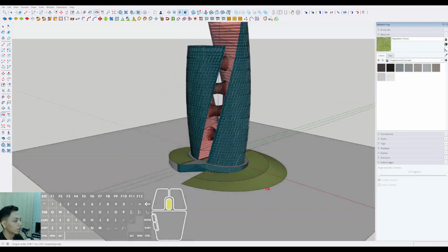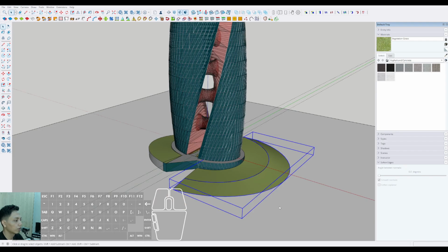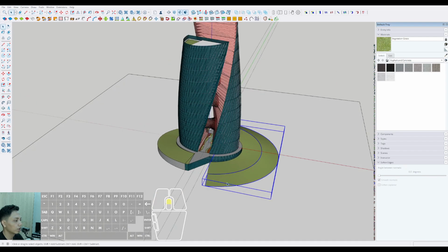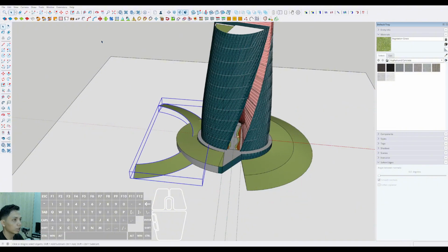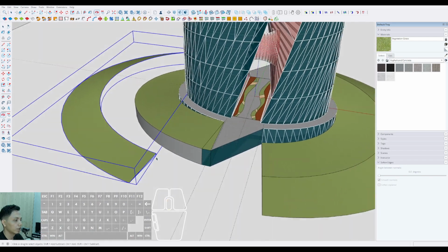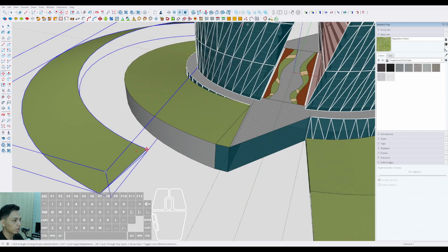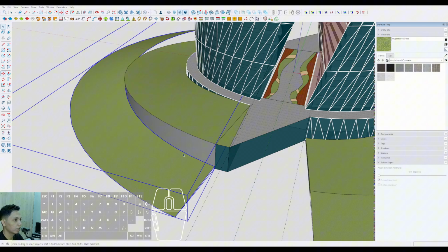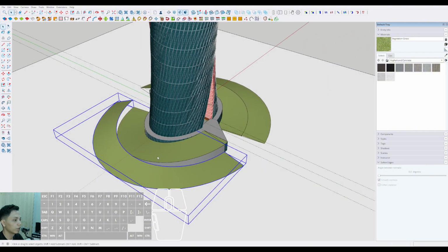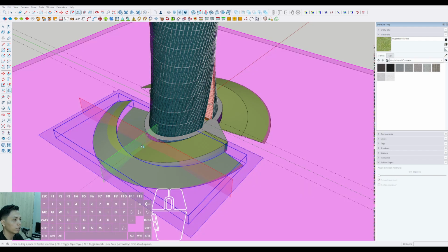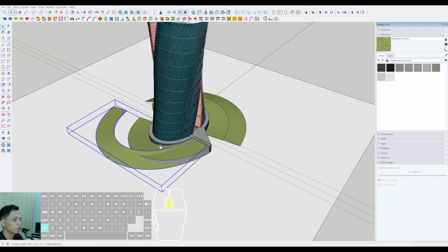Okay, you can see about the result, and you can also make a component, just create, and you can select move, press Ctrl till this position, and select the mirror and mirror on the red axis. Well, now you can move to the correct place over there. You can mirror again to the green axis.